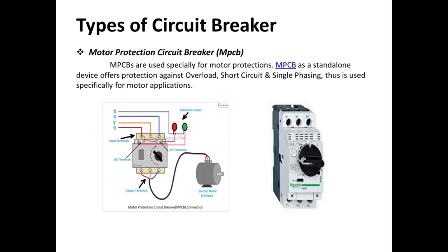And next is the motor protection circuit breaker. MPCBs are especially for motor protection. As a stand-alone device, it offers protection against overload, short circuit, and single phasing. Thus it is used specifically for motor applications.